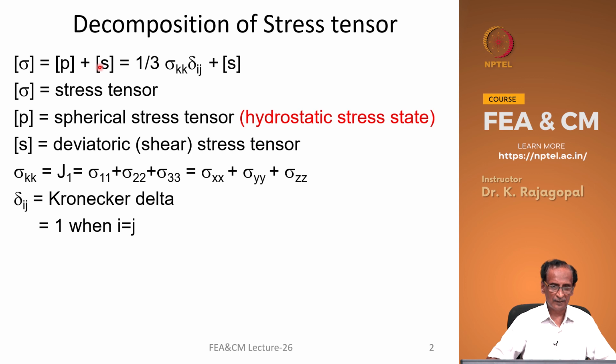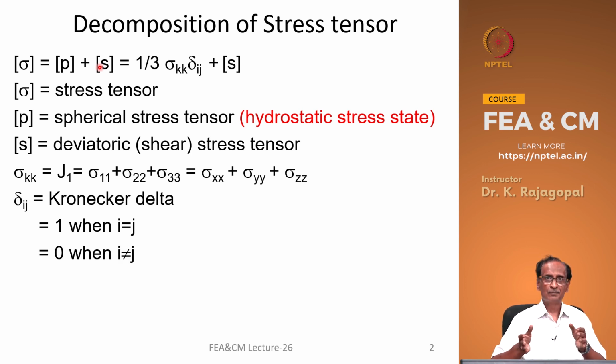and then we can actually control our parameters. See, there are different modulus terms like the bulk modulus that controls the volumetric strains and the spherical stress tensor, and the shear stresses are controlled by the shear modulus. The shear stress is G times gamma, where gamma is our shear strain, and by playing with these numbers we can approximately simulate the strength of the material and so on.